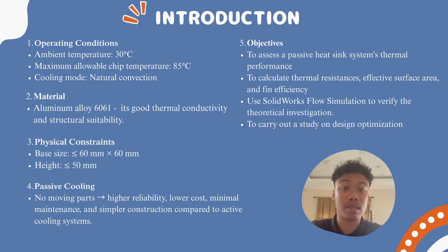Second is the material. For this case, we are using aluminium alloy 6061, which is good for thermal conductivity and structural suitability. Third is the physical constraint. The base size for this chip is 60 mm by 60 mm, and the height is less than 50 mm.